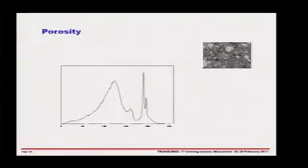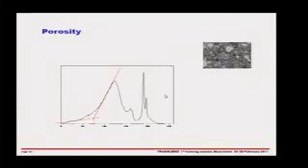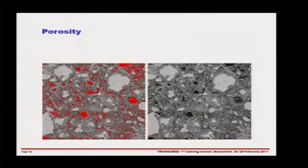Now, this just shows the secondary electron imaging, same thing. We can't well identify the pores, but we can do it in a way that's the same every time. So what we generally do is this. We construct a line here, we construct a line there, and we say, okay, let's take this point here. It's fairly arbitrary, but the question is, does it compare with other methods? And when we do that, we find that it gives you a very good idea about the large pores. You can see the dominance of these hollow shells again.